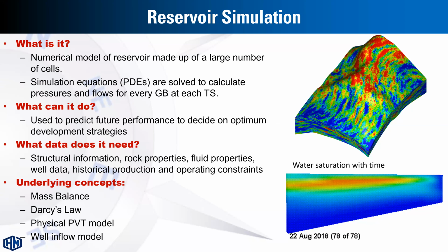And the last principle required is the well inflow model or the IPR model to characterize the fluid behavior at the sand face, at the interface between the reservoir and the bottom of the well across the well completion.